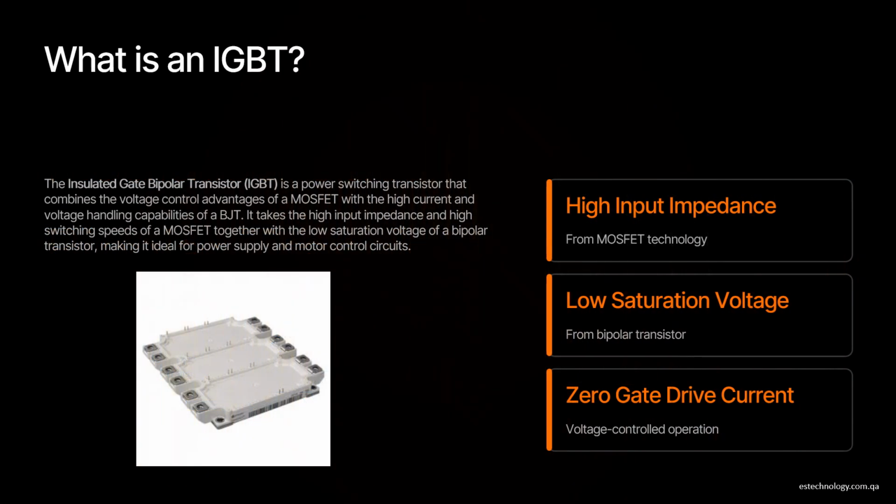What is an IGBT? The Insulated Gate Bipolar Transistor, IGBT, is a power switching transistor that combines the voltage control advantages of a MOSFET with the high current and voltage handling capabilities of a BJT. It takes the high input impedance and high switching speeds of a MOSFET together with the low saturation voltage of a bipolar transistor, making it ideal for power supply and motor control circuits.